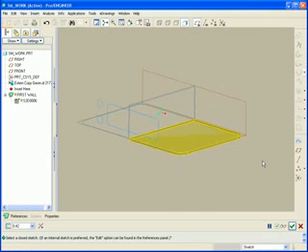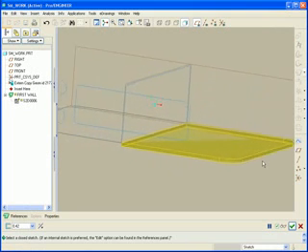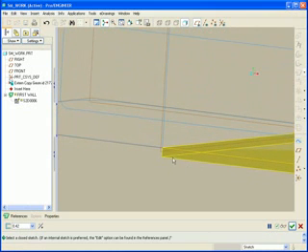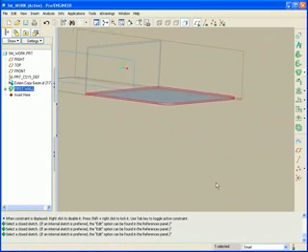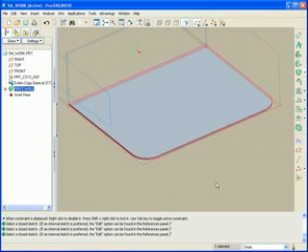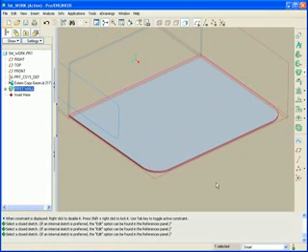Now let's take a look at this. The curves describe the outside shape, and you'll notice here the sheet metal is already on the wrong side. We'll bump that with the flip arrow, and then we'll change its thickness. Let's go with a 0.2 thickness. So this might be our flat. So, relatively easily, use Edge.